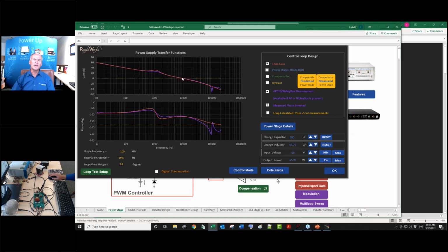And then once it's crossed over, you will run into systems, especially those of you with multiple loops, where the gain can start approaching 0 dB again. So you're looking for gain margin in here as well. How far is this before it starts going unstable? Now the phase, again, goes unstable in the measurement about that point. You never try to cross over there anyway, but the predicted phase never goes unstable. So you kind of get a false sense of security from the prediction, and if you don't measure, you don't realize, well, it's not really going to behave that way.